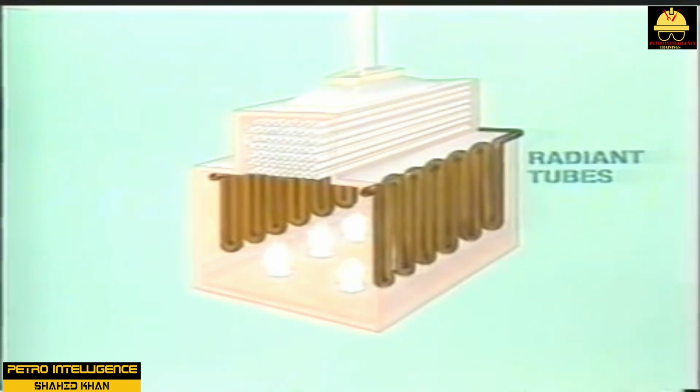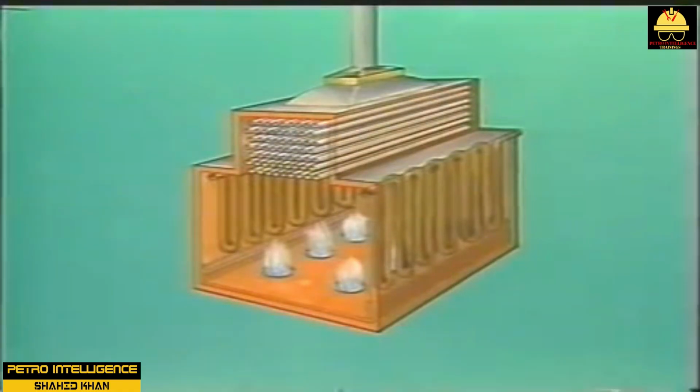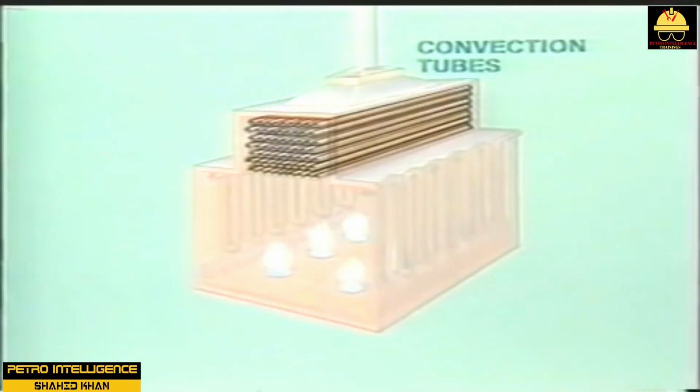In a fired furnace, radiant heat is emitted from the combustion of natural gas or light oil. As the radiant heat travels from the bottom of the furnace, contacting the tubes or passing in the furnace, and then continues to the top, heat is transferred to the surrounding air. This process initiates the convective heat transfer process that causes the lighter air and hot combustion gases to rise above the radiant heat source. The top of the furnace is referred to as the convection section because most of the heat it receives is by convection.